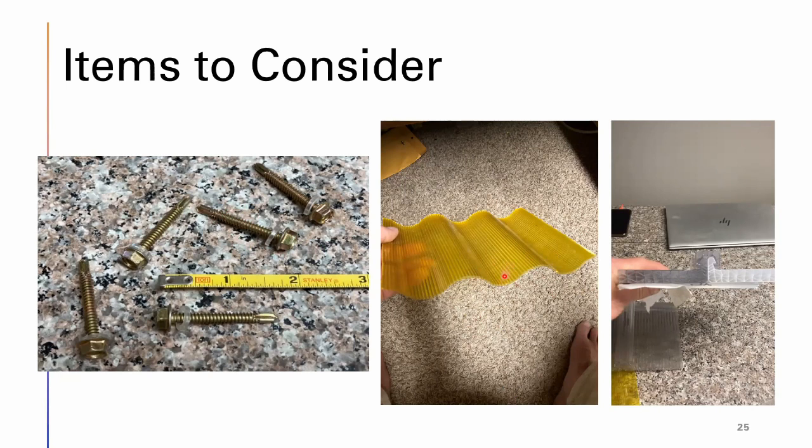Now, if you buy this stuff at Home Depot, there's no air gap. It's just a solid. And as I stated before, in a solid, there is 0 protection from radiative heat transfer. You have to have an air gap in your glazing. Whether it's 2 layers of polyethylene, that's how a lot of people do it. They use a blower and expand that interstitial space between the 2 polyethylene layers. Or if you use polycarbonate, just flat, solid polycarbonate does you nothing in terms of protecting your crops. You have to have 2 layers.